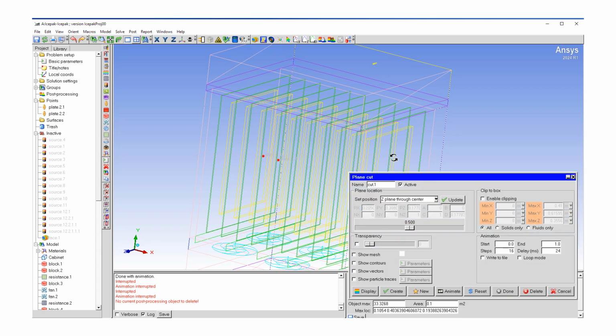This is also very useful. This plane, which we define, can be at a constant x, y, or z direction, or you can define to a point and normal, etc. And it's going to cut through all of the objects. So if we do y plane through center, so somewhere roughly here, for example, we can look at the mesh.